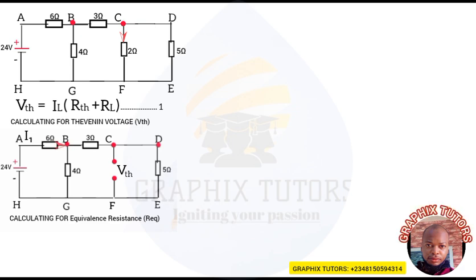And when I1 flows to point B, what happens? It splits into two, I2 and I3. The I2 will be flowing through the 4 ohm resistor, and the I3 will be flowing through the 3 ohm resistor and continue flowing until it gets to another node C.